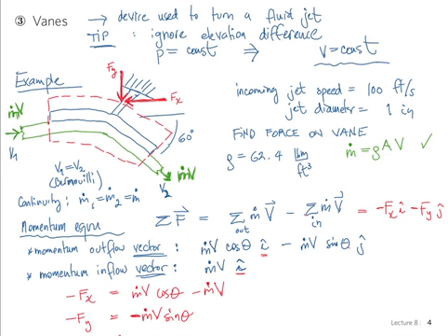So you have now seen that we are able to calculate all the forces. I'm not going to go through the algebra of manipulating the numbers themselves, and I'll just give you the answer in terms of numeric values, and you can check this in your own time. 53 pounds force for the x direction, and the y direction is 91.8 pounds force.